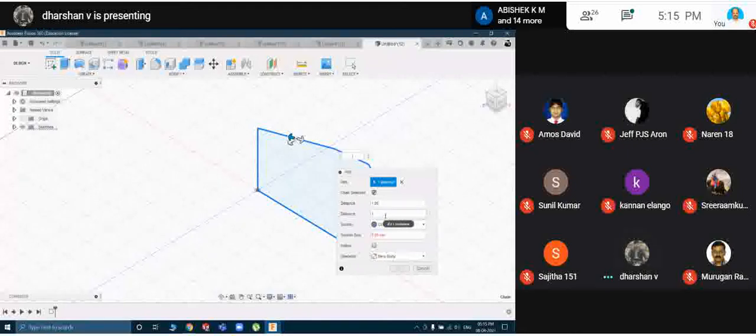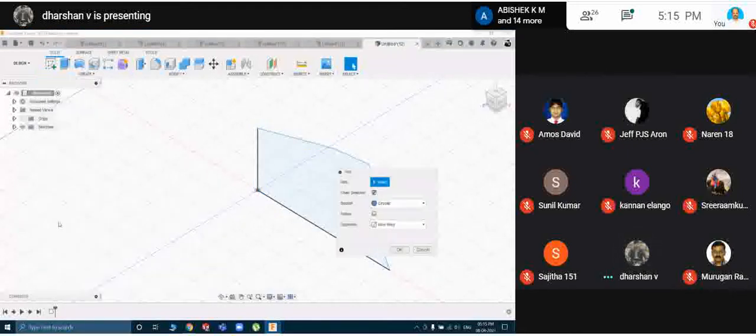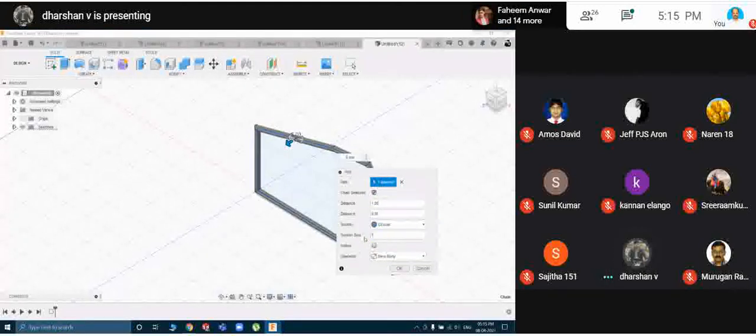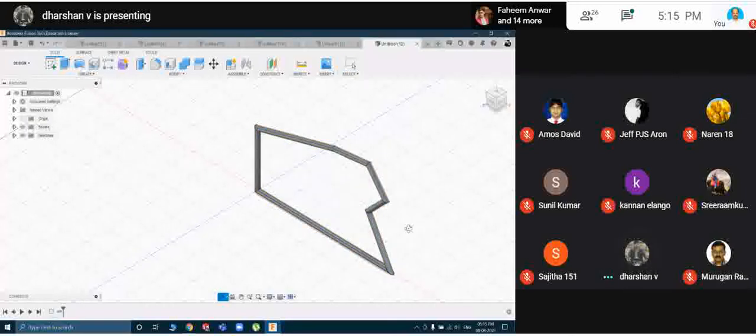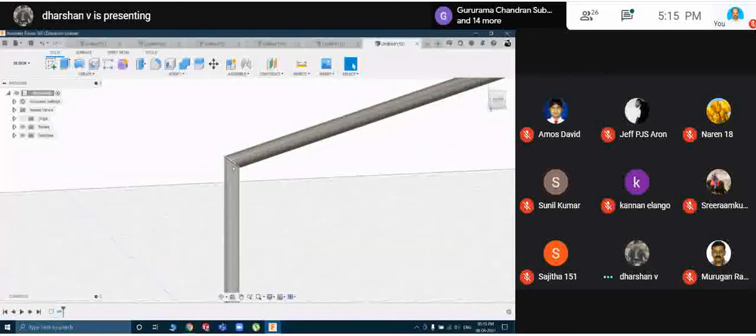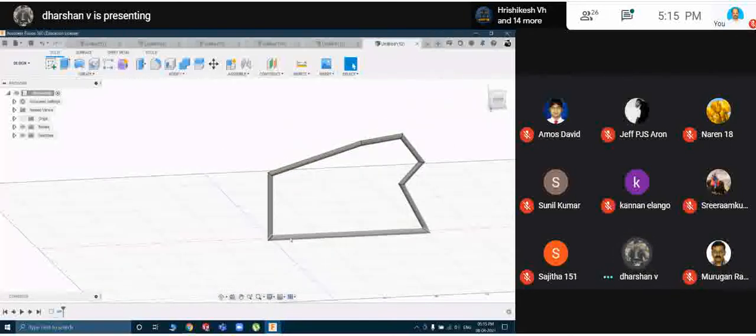Sections are distance. And do it again. Pipe. Clicking this. Section size is 10 mm. I don't want it to be 10 mm. Let's say 5 mm. Okay. Good. I've designed a bike frame in just a few seconds. That's all. All this feature and all now automatically based on how it comes together, it will be designed.